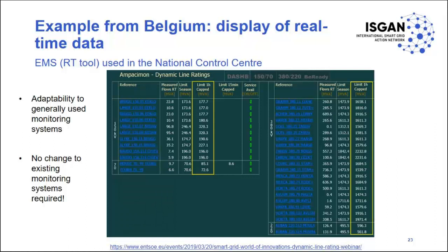and we provide standard frames. Here it's ICCP frames, but it could be IEC 104 or DNP3, IEC 101, or whatever, as long as they follow an international standard. And so these frames contain the data that are computed or measured by our sensors and our algorithms.